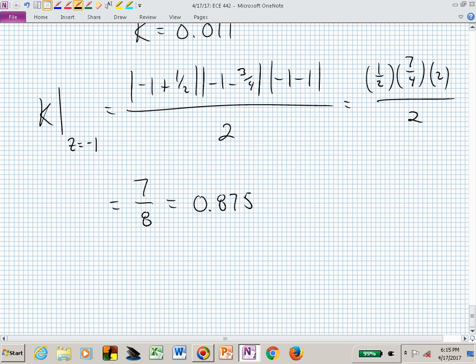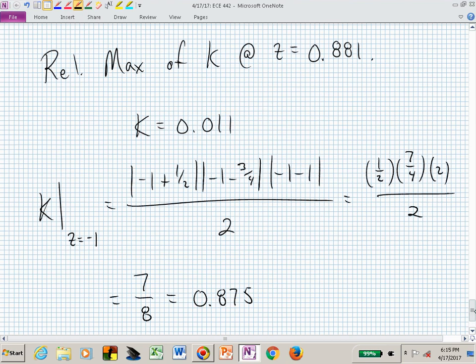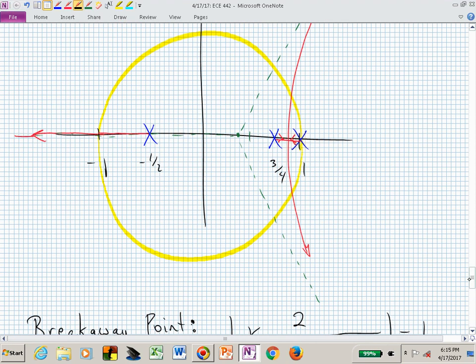Probably these two poles that broke away on the right-hand side are exiting the unit circle before 0.875. And if you sketched this accurately, you could eyeball or pretty much measure on your graph paper where that departure point is. If you have a compass and you draw your unit circle and you've found the breakaway point as 0.88, now you just start zipping off to those asymptotes.